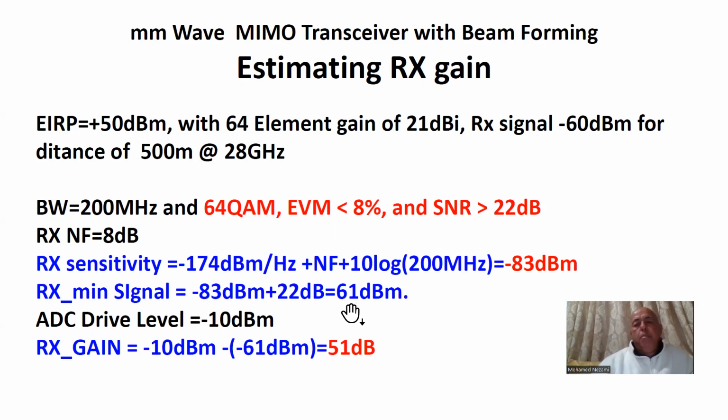With minus 10 dBm, that means now you take this signal, which is minus 61 dBm, and you need to amplify it by at least 51 dB, say 50 dB, and that's the overall gain of the receiver. So now you have to add some variable gain out of this. You're going to make at least, say, 20, 30 dB of this variable, because this is really at the minimal detectable signal. You're going to have a much stronger signal as you get closer to the cell transmitter point, in which case you're going to have to reduce the gain.